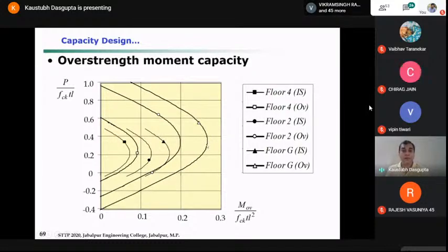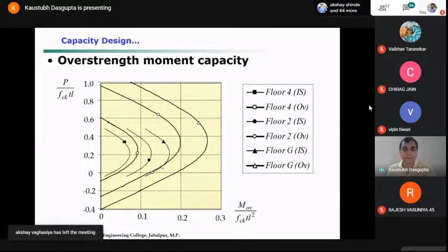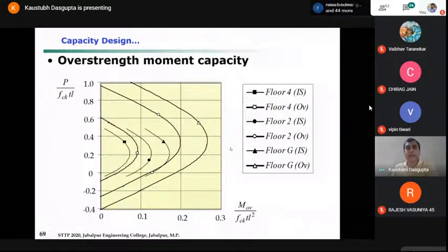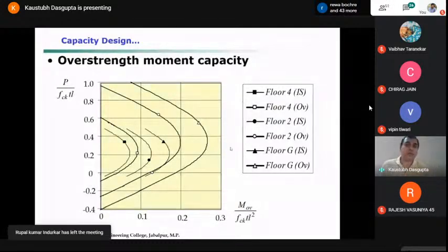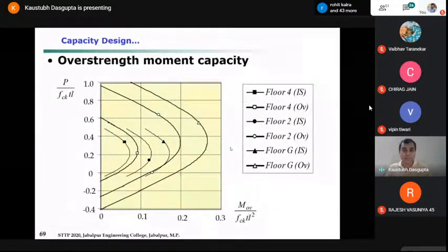So with this increased moment, your applied shear force is also high as compared to the design shear force compatible with this design PM curve. So these smaller ones are from the design stress strain properties. These lines with the larger thickness are for the actual stress strain. So that gave us a good insight that in real earthquake shaking, when you are talking about the overstrength of beam, column, wall, how much additional shear force gets mobilized, which can make the structure unsafe. If you have not given enough margin in the shear design, it can lead to shear failure.